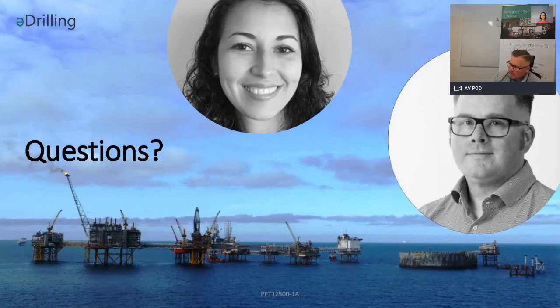what's called differential stuck. We don't predict that is happening at the moment, but we are all the time monitoring and observing, or the system is doing that, to detect when a problem starts happening. That means that while you're drilling and on one connection, and the system sees that there is a differential stuck, you get information about that, and that is used later on to detect if it gets more severe than it was.